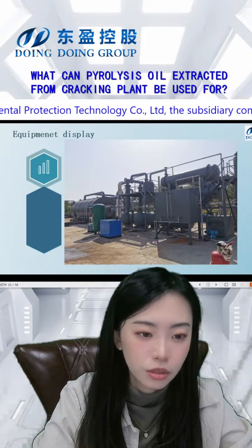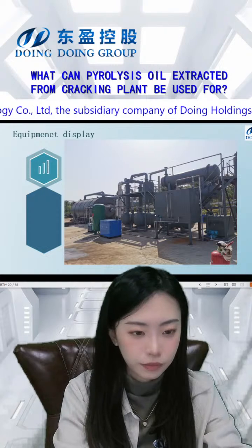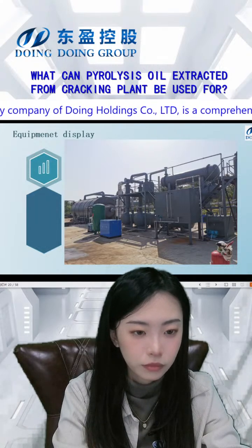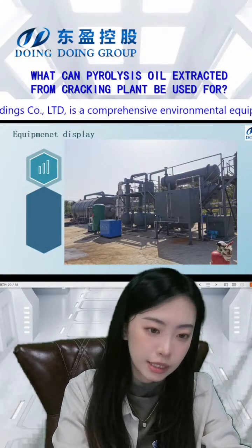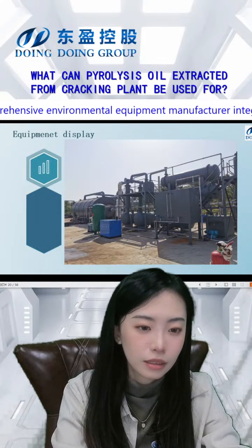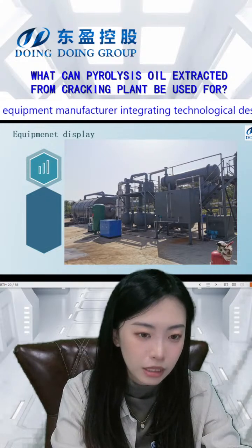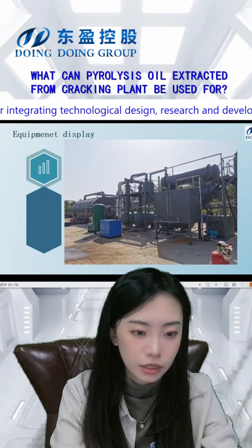If we use this vacuum device, we can solve this by pumping the oil gas to the condensation system for maybe 1 hour. Then there is no oil gas remaining in the reactor, so there is no chance of a flash explosion.